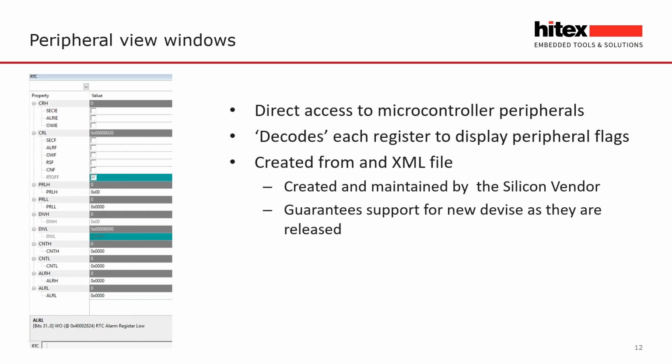Now, when you're working with a specific microcontroller, in most debuggers there is a set of windows that will allow you to see the current state of the peripherals within the microcontroller. As the number of Cortex processors started to increase, developing these windows became a bottleneck for all the people making debuggers. There may be something like 10 to 20 windows within a given microcontroller, and then many, many different variants. So they became quite an issue to develop.